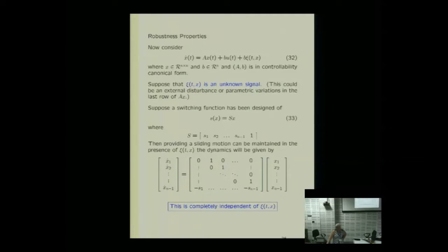Yes, and indeed we will see that in some of the work that we do later with higher order sliding modes. There is no need to reduce the order of the dynamics if you don't want to. There's been a lot of work in integral sliding modes, and that uses the full order of the dynamics. So it is not the case that you have to, by any stretch of the imagination. If you don't, then you will typically need more signals, so you will have a dynamic controller typically. But there's no reason in principle why you don't have it as the order of the system, or indeed of an order greater than the system. You know, there are some controllers which actually add compensator states to the dynamics and develop sliding mode controllers.